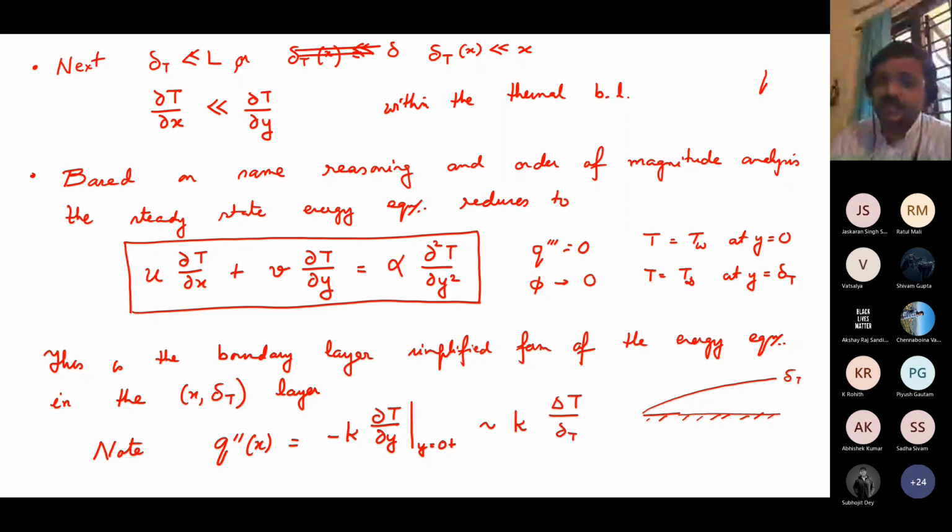But here it's opposite. Okay, so that's why I said in the last class that when we are talking about cooling applications, etc., it's always a give and take. It's optimization. Okay, I want a lower thermal boundary layer thickness, and so my shear stress is going to be higher, but my heat transfer is also going to be higher.